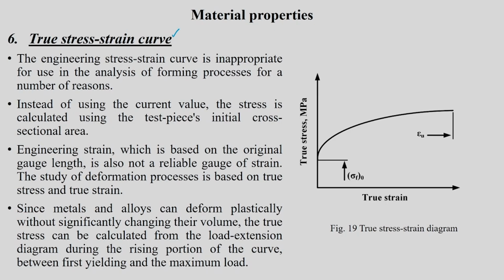So, now if you want to really get the real picture of the deformation, then one has to have some curve which is depending on the instantaneous dimensions, which is nothing but your true stress strain curve. Since metals and alloys can deform plastically without significantly changing their volume, the true stress can be calculated from the load extension diagram using the rising portion of the curve, that is nothing but your plastic deforming region between the first yielding and the maximum load.